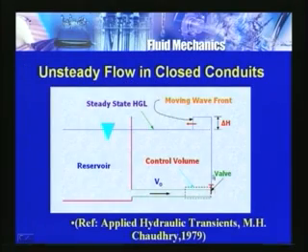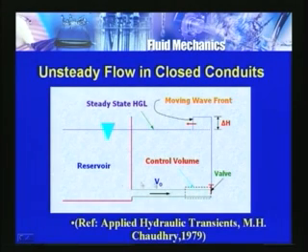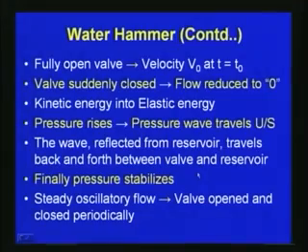The wave is again reflected from the reservoir and travels back and forth between the valve and reservoir. It goes back and returns like that for some time, until the intensity of the pressure reduces, the water hammer effects reduce, and finally the pressure stabilizes.